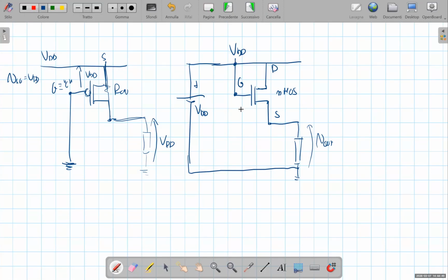The control variable of the NMOS switch, which decides the conduction of the switch, on or off, is the gate source voltage. If I put the gate to a high voltage and the source voltage is low, clearly the device is turned on. But in this configuration, when the output goes high, the source voltage is no longer zero.